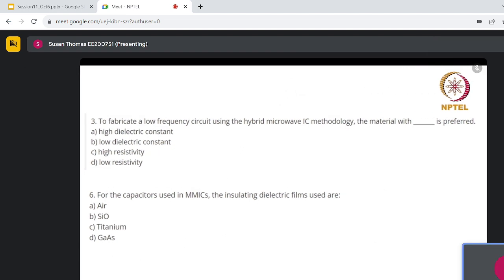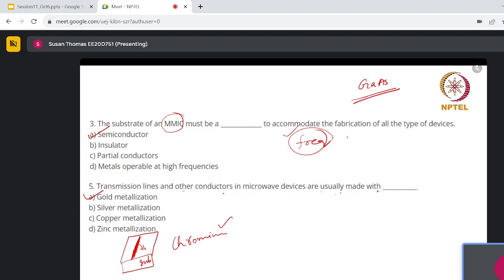Yes, I understand. So when we talk about metallization, the most desirable one is gold. We can also have other metallization for conductors. There are several options, either silver or others. The most desirable one is gold, and it depends on the application, especially if you can't compromise the conductivity of this part, then we go for gold.